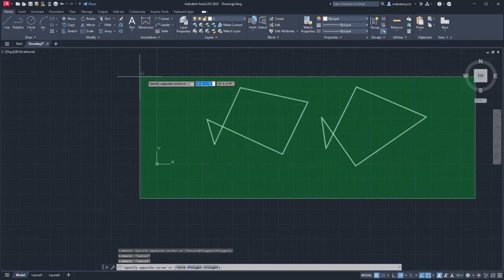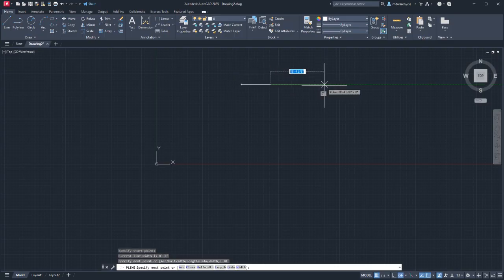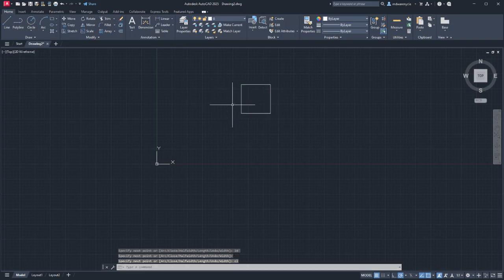An example, and we'll be using this very shortly for your milestone this week, is if I was to draw, say, a 10 by 10 cube, 10 foot, 10 foot, and then I can snap object reference here. Another option I have is CL, which will close. It'll send the point to the initial point here. So now I have these 4 lines right here, and I can run an offset command, 6 inches, and offset that.